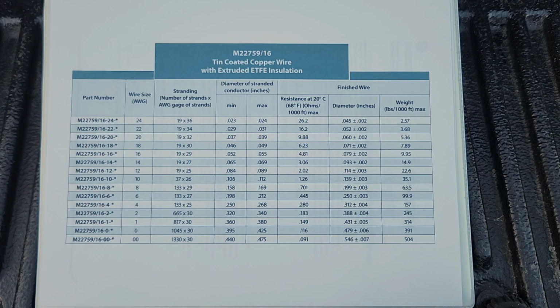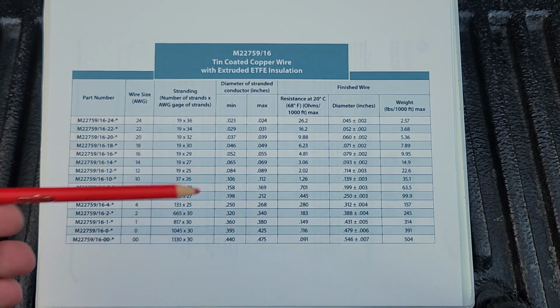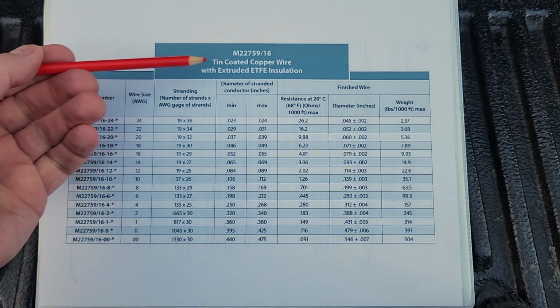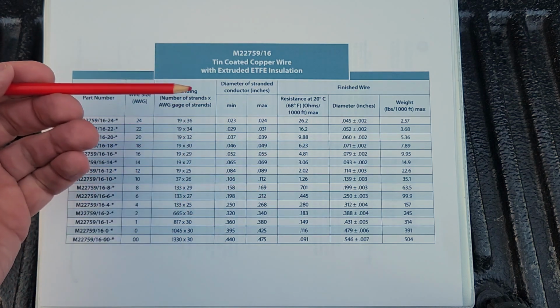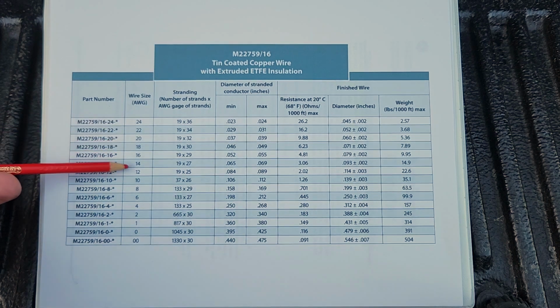If you're an engineer or know the basics of Ohm's law, this ampacity table might be better for you. It gives you a little bit more flexibility in doing some of the calculations. What you see here is an ampacity chart for milspec wires, so stuff that you'd find in airplanes and military vehicles, and you'll see a row for every gauge.